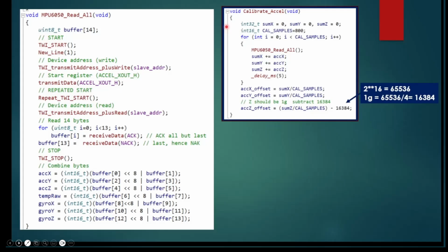So you always have a little bit of the acceleration, the gravity vector, a little bit tilted, just a tiny bit. Or not. But what you want to do is, with no motion at the start, see if you need to do any calibration. That means that it doesn't mark 0.